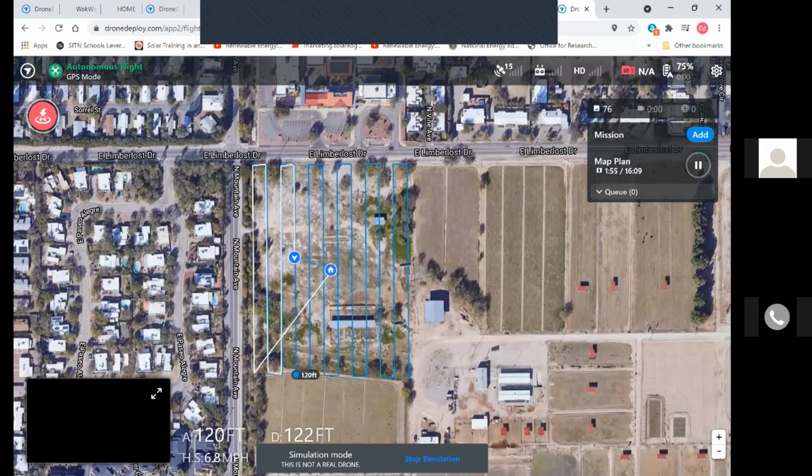Drones, typically the batteries only last about 15 to 20 minutes, depending upon wind conditions, the temperature outside, and how high you're flying. And in some cases, I may be mapping a field. It'll tell me I may need 2 batteries, or maybe my battery was not full when I went out and started flying. The program will indicate that in the app. It'll say it's a low battery. When it gets to about 20 to 25% battery state of charge, it'll start flying and beeping. And then the drone will bring itself back.